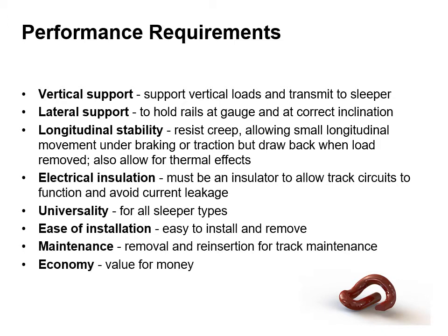In terms of performance requirements, these are summarised below and include supporting vertical loads, transmitting these loads to the sleepers, maintaining gauge and inclination, resisting creep, allowance for thermal effects. They must also be an insulator to allow track circuits to be maintained. They must also be easily installed and removed for maintenance purposes. And most importantly, they must be economic, i.e. value for money.